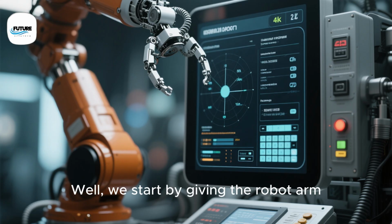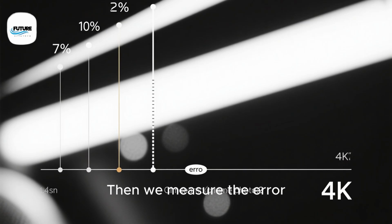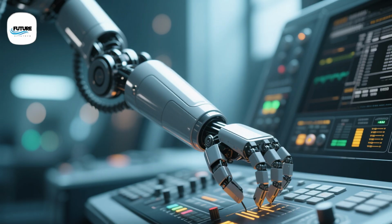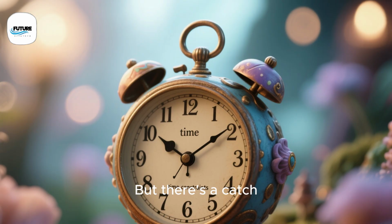Well, we start by giving the robot arm some initial parameters, then we let it move the block from point A to point B. Then we measure the error using the cost function and see how far away the block is from point B. Next, we use gradient descent to update the parameters of the robot arm in the direction that will minimize the cost function. Repeat this process over and over again until the block reaches point B, and we get a cost function value of 0. There's a catch.